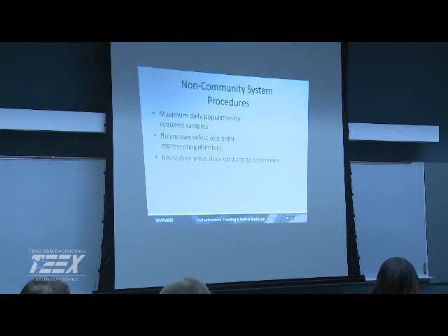We'll get into some disinfection and all of that a little bit later. And then we talk about the recreational areas. So do you still have to pull bacteriological samples for your area? Okay, how many do you pull a month? It's not every month, they're on quarterly. Oh, are you? Okay, all right. Are you pulling the samples yourself, or do you have somebody else come out? Who's running the samples for you? I send them to Knoxville. Okay. And are you shipping them overnight?